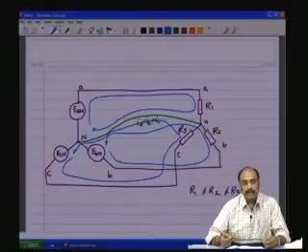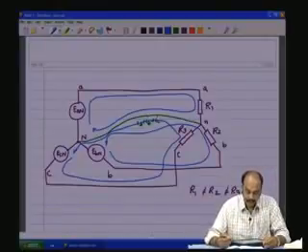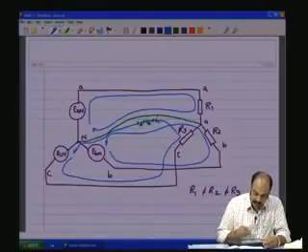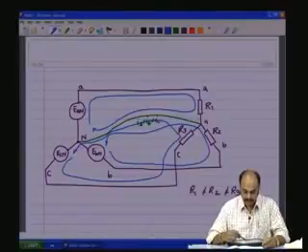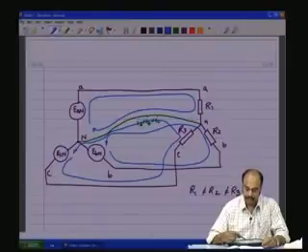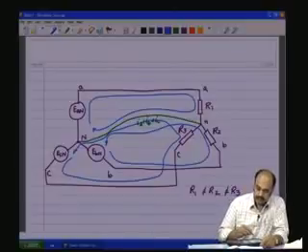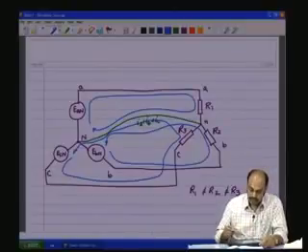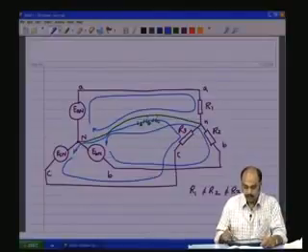The voltages across all the three phases will still be the same as decided by the source, whereas if this green line, the neutrals, are not connected, then the unbalanced currents will get mixed up and flow through the other loads, and then you can have voltage distortions. So, in a star, to take care of the unbalanced load, you would normally connect the neutral points.